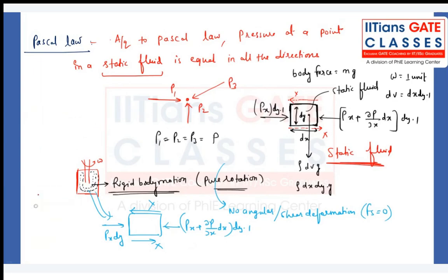See, in a fluid element there are two types of deformations. Remember that. One is volumetric deformation. Volumetric deformations happen because of the normal stress present there. Second, there will be some shear deformations. Whenever we do the derivation of the Navier-Stokes equations, whatever normal stresses are acting on a fluid element, we categorize into two components: one is volumetric deformation, the second is shear deformation.